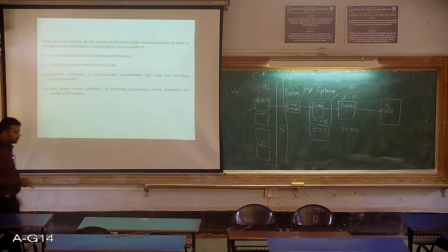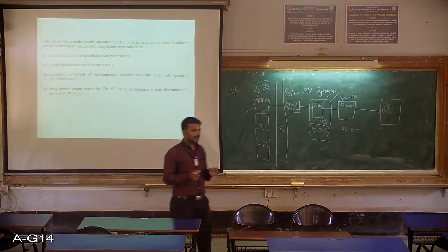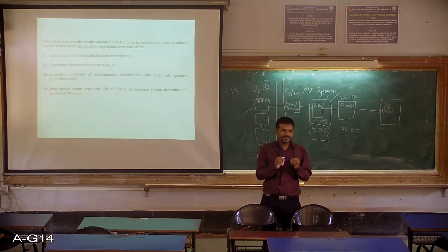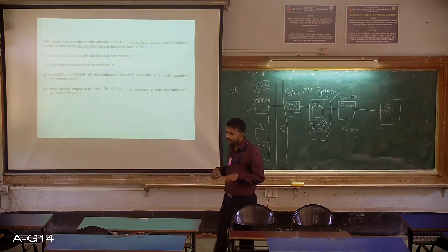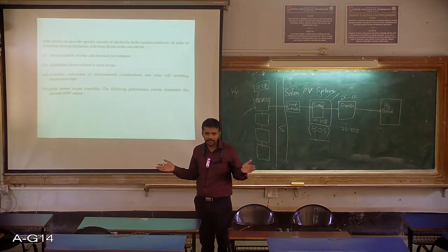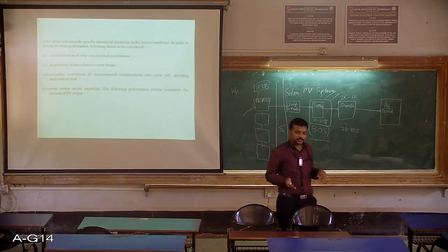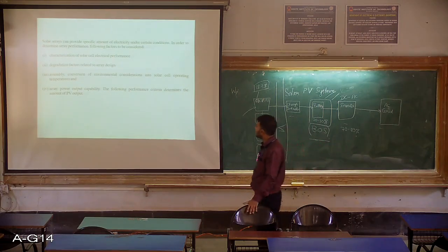design. It depends on the array design, how we are placing the arrays, at what distance we are placing. So all these designs come into the picture. That is the degradation factors. If we keep the arrays very close to each other, then the shadows may fall on each other. Those kinds of conditions and inappropriate designs, all those things we can consider as degradation factors